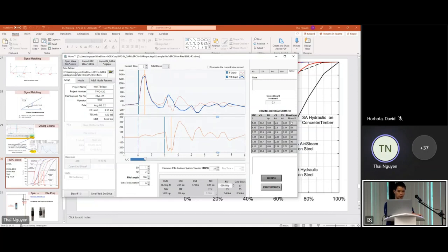So that is the stroke height and blow count here for driving criteria. This process is targeted for driving criteria. As such, it is very simple, much easier than CAPWAP. With CAPWAP, you have to do a lot of manipulation in terms of pile cushion and efficiency.